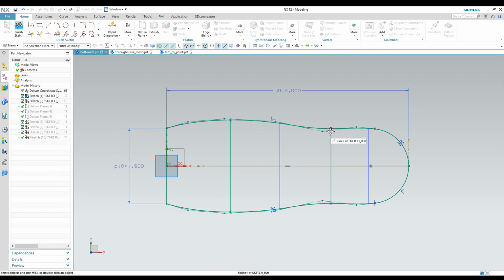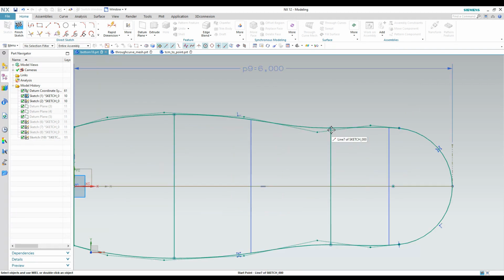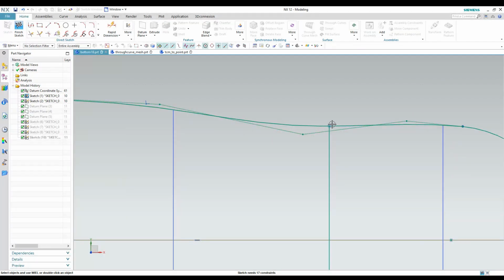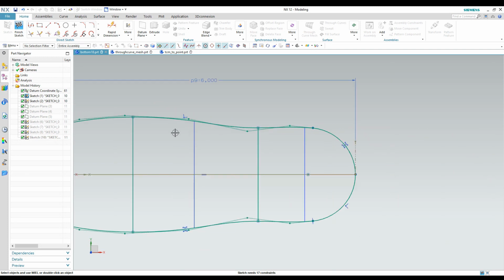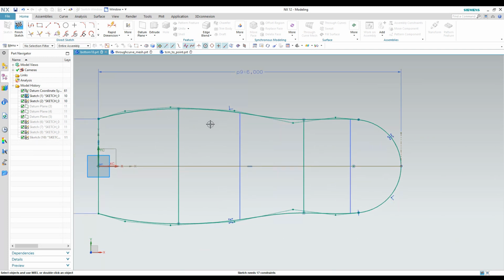So I don't have to worry about where these lines come into contact with them, if I move something or change the shape a little bit, them coming into contact with a different curve. So like here, there would be a transitional point between this radius and this radius. And if one of my strings moved past that, I would have problems with my surface and my sketch potentially. So anyway, that would be something to think about when you're creating these.